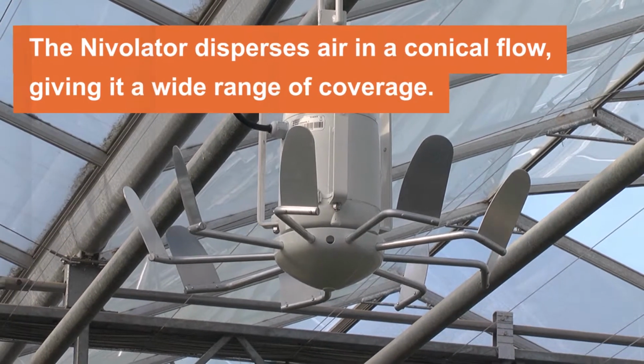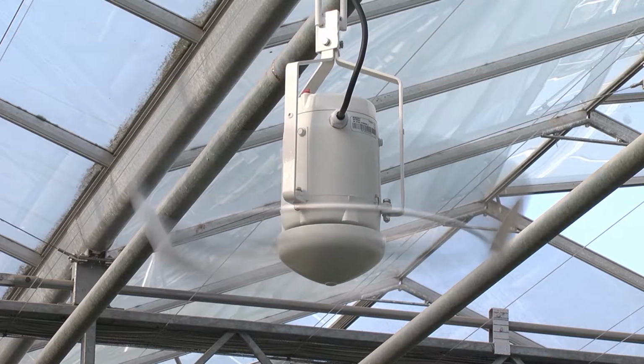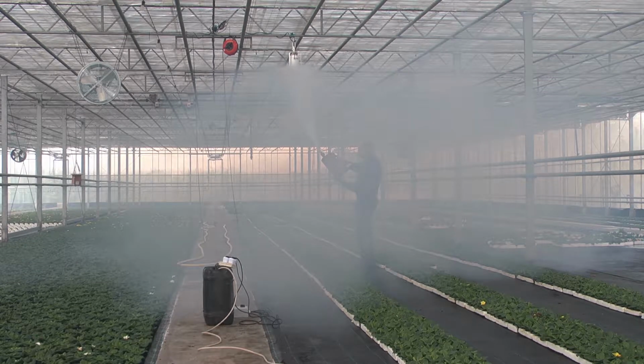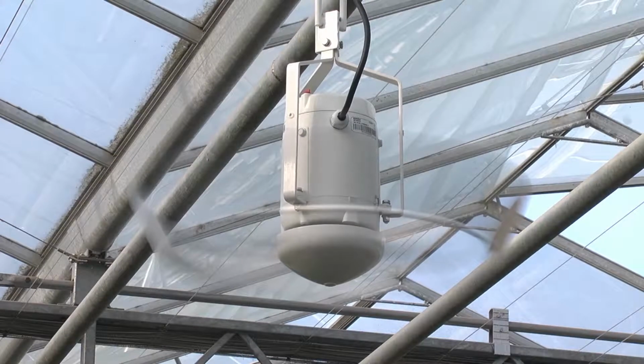Horticulture-specific vertical fan designs, such as the nivelator, disperse air in a conical flow, giving a wide range of coverage. Air is drawn from both above and below the fan, creating a local circulation pattern. Depending on the height at which the fan is mounted, each unit can cover a diameter of around 15 meters. While this can mean more fans are required, the aim should always be to deploy the most effective solution to promote air movement for any given crop.